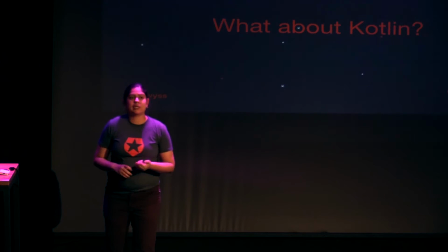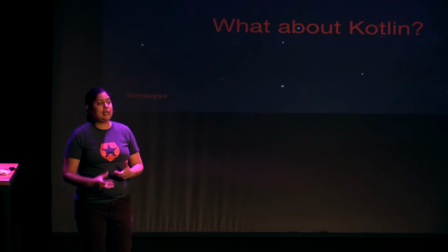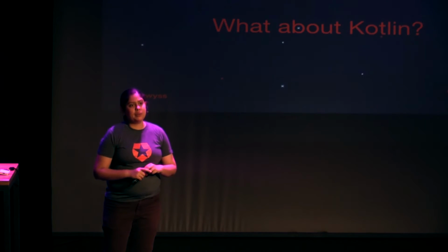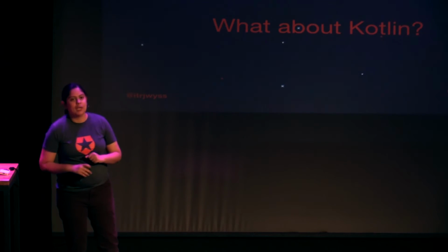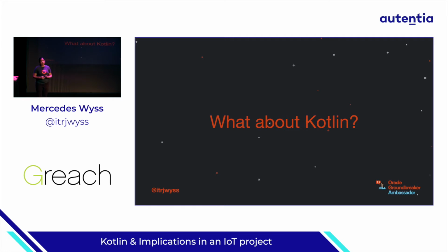So if I am not using, for example, Kotlin Native, if I am using the Kotlin that is compatible with Java, that is interoperability, I will need to run this Kotlin over a Java virtual machine. So people don't like to use it. But we can use Kotlin Native, though Kotlin Native is not designed for IoT projects. If we want to use Kotlin, we need to do something similar to Java, which has the Java Native Interface to connect with native code, that is C code. So we need to use some C libraries to connect with the GPIOs. And we need to package our Kotlin application with that and root for running Linux applications. So it's not precisely friendly.